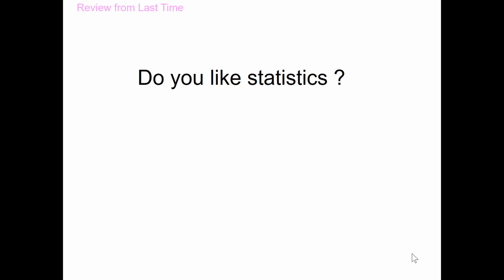Of course, you might be surprised the other direction and say, wow, this device has a great yield, much better than I expected. That's really a rush, right? Will your boss be impressed if you have a part that has a much better yield than you expected? Well, be careful, because that usually comes at a cost. The enhanced yield is likely due to you putting too much area into the circuit. And more area means more cost.